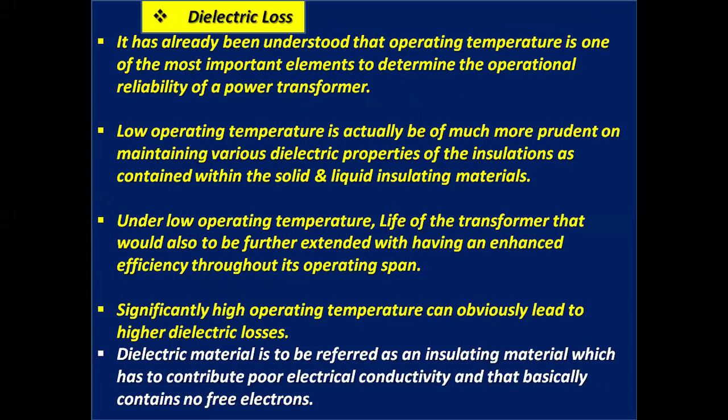Dielectric loss. It has already been understood that operating temperature is one of the most important elements to determine the operational reliability of a power transformer. Low operating temperature is much more prudent for maintaining various dielectric properties of the insulations contained within the solid and liquid insulating materials.